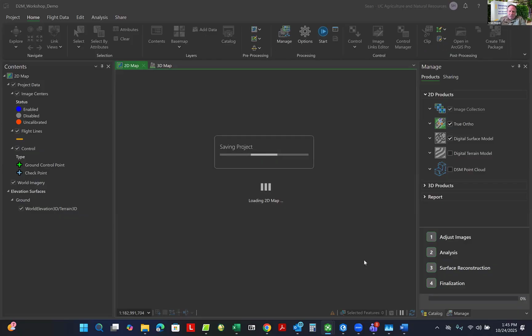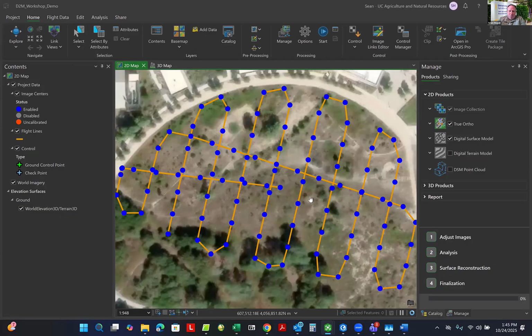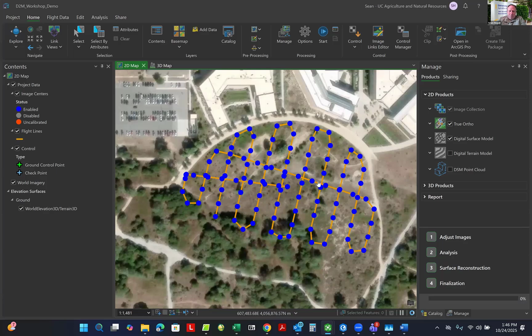It'll take a second for it to come up. This, by the way, will be the workflow that most of you will probably do, assuming that you're not using ground control targets, which requires a very high precision GPS unit like a Trimble Geo7X or something to that effect. Bad Elf with vicarious calibration, or rather using ground station data to correct it, differential correction that is. But most of the time, you'll bring in your RGB image just like this.